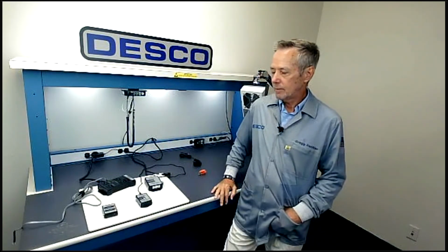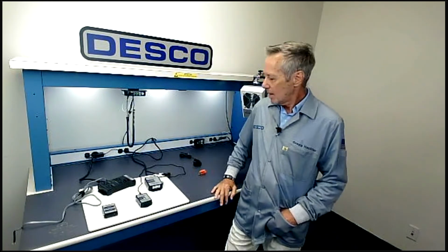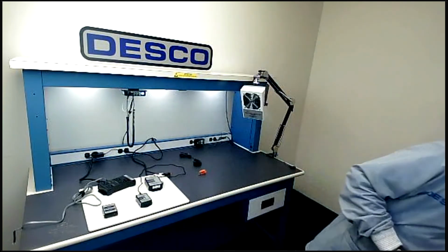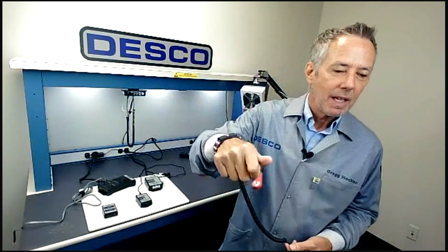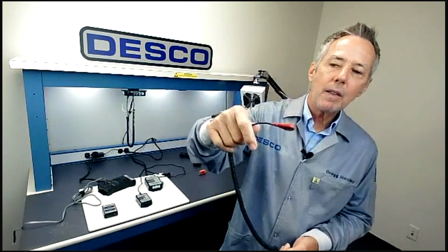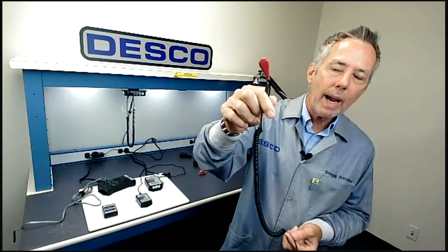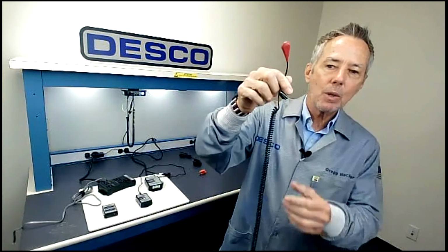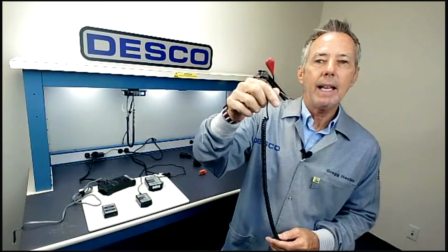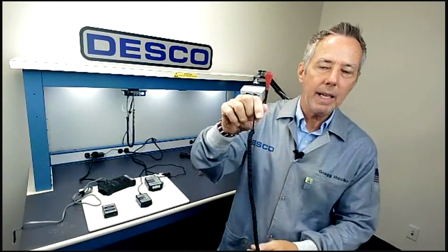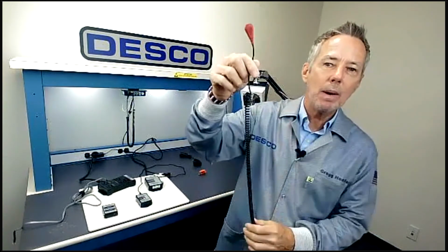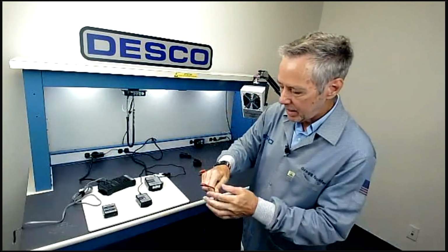Can you demo a low limit fail? What that would look like? Yes, I can. I'm going to reach over here and grab a cord. This coil cord in my hand has a red head on it. The ESD Association standard requires that if I have any personal grounding item that is less than 1 megohm, you have to identify it with the color red. So this is a coil cord without a 1 megohm resistor, and it's colored red.